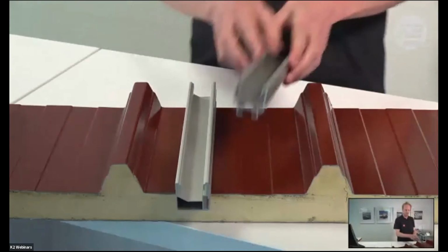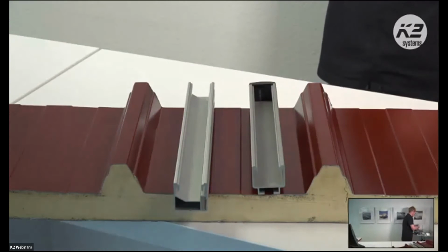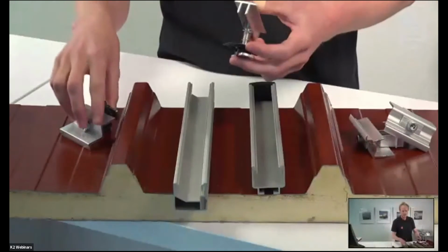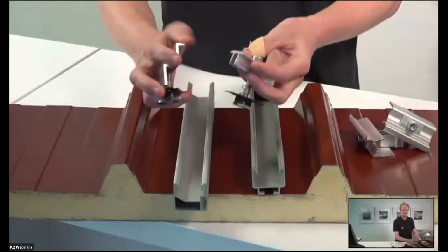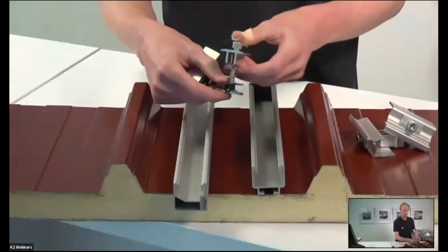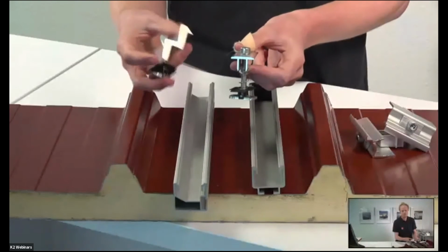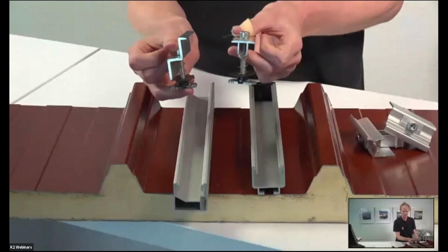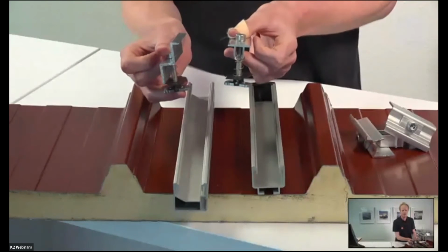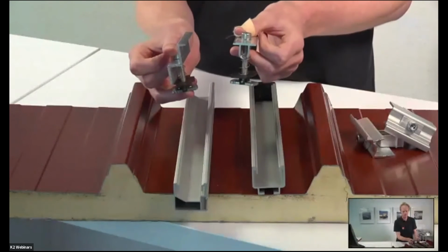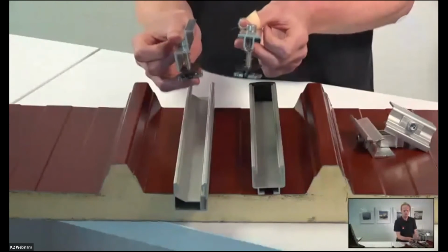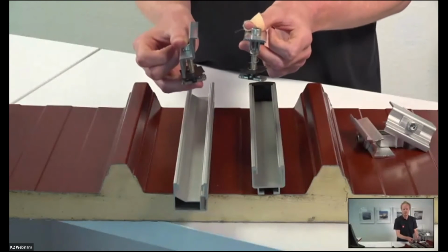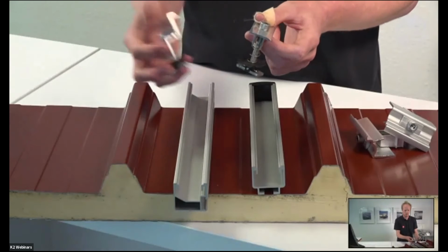Just to show you the clamps that will be used here as well. We have two styles. I have some examples here. So here we have our standard clamps. So these clamps are suitable for modules of depth 30 to 50 millimeters. I should point out that there is a different clamp for each module depth. However, you don't have to worry about this too much, because our software, which Roman will show later, pre-assigns the right clamp for the module size that you would like to use. So all you need to do is put in your module size, and the clamp will be selected for you.